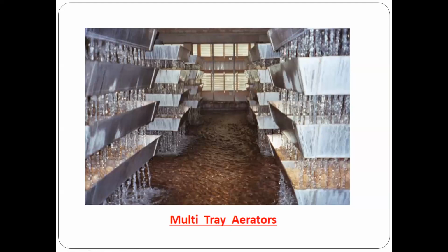Which have a size of 50 to 75 mm. And we have to keep whatever horizontal bed we are providing on these trays at nearly 20 to 25 centimeter height. 25 centimeter height, and whatever spacing we are providing, 40 to 60 mm. That spacing is to be provided.